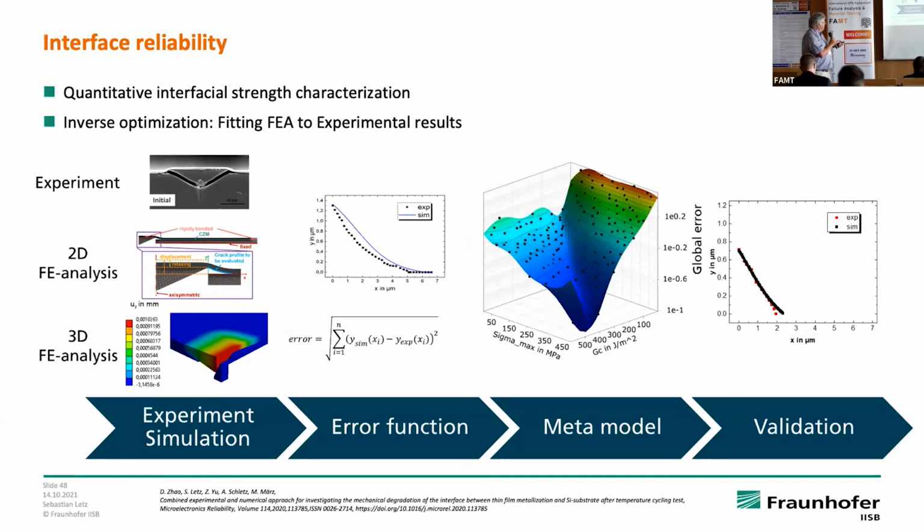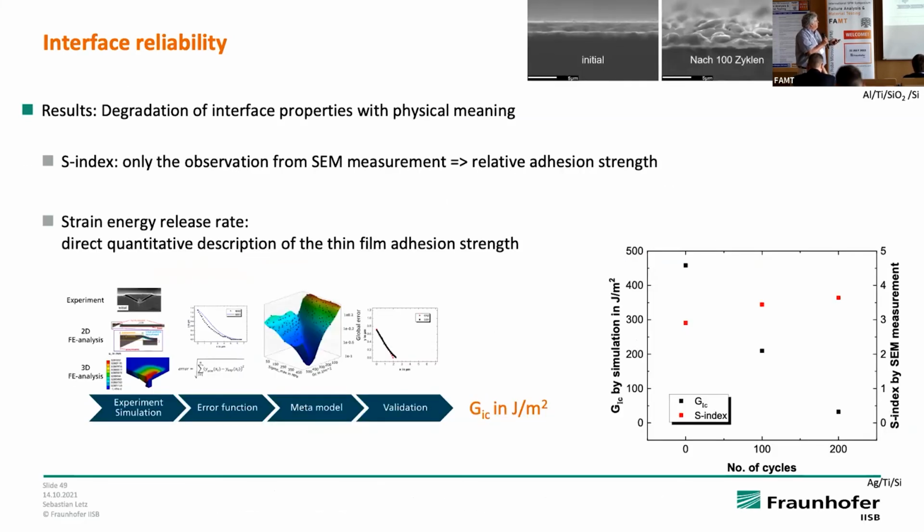So we do the experiment. We do a parameter study on the adhesion forces, or the surface energy basically is the target, and we benchmark and validate it against our experiments. And the important point is that we really get a number for the surface energy of a thin film on top of silicon in terms of calculating adhesion, and use it in reliability models when you want to do reliability prediction.